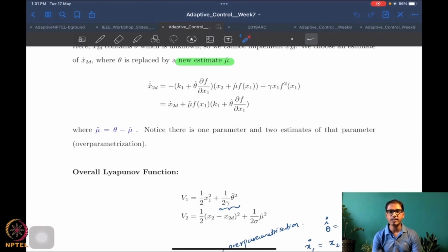This is another thing that I want all of you to get used to. Suppose I think of any robotic application, say a 2-arm manipulator, or a quad rotor. A quad rotor has 6 degrees of freedom, so 3 rotational and 3 translational. Corresponding to that, there are 12 states: 3 position states, 3 linear translational velocity states, 3 angular position states, and 3 angular velocity states. So there are 12 states. So they are vectors, and we describe the equations in terms of vector equations.